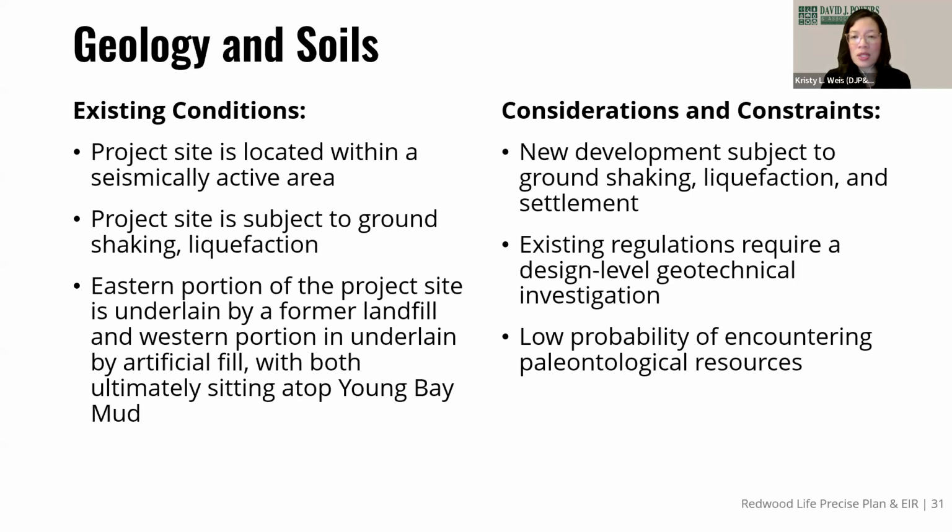The site has a low risk for lateral spreading because of the underlying soil conditions along the slough, and likely has low to no risk for landslide given the relatively flat nature of the site. Pursuant to existing regulations, including the California Building Code, development on site would be required to prepare a design-level geotechnical investigation to address seismic and seismic-related hazards.